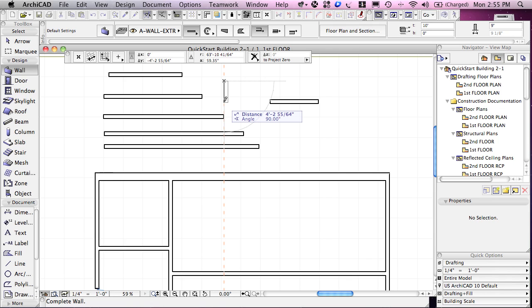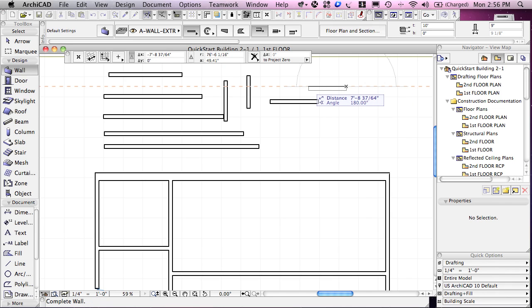You can type in, for example, a letter, Y, and then type in -8, and that will accept it. Let's just turn off the tracker and see how that works. So I'll click here, and I'll type in Y, and you can see it highlights it. And I can say -6 feet 6. So it will still work, but the reason why the tracker is simpler to work with is that you don't have to type in coordinates in most cases because it actually understands the direction that you're going as a distance. You can see how it says distance rather than X or Y.